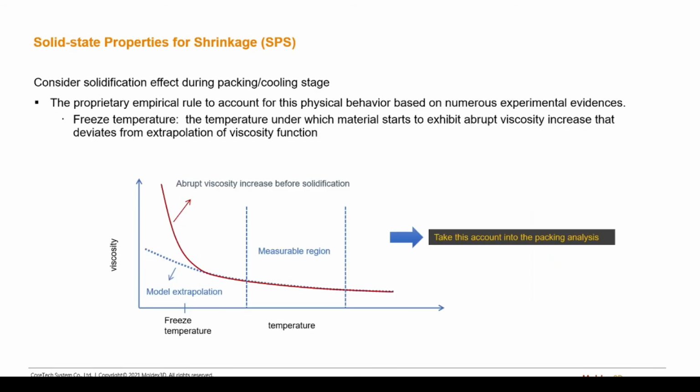A new enhancement has been made to our warpage calculation, what we call the SPS, solid state properties for shrinkage, considers the solidification effect during the packing and cooling stages. This is an empirical rule to account for the physical behavior based on some numerical experimental evidence.